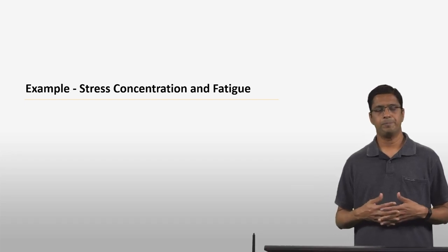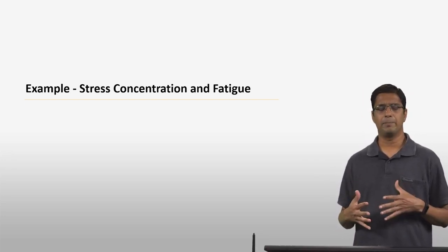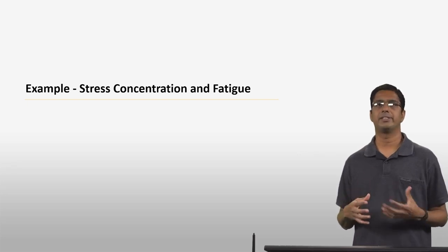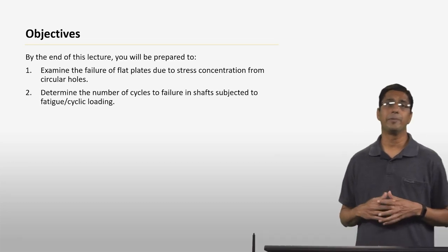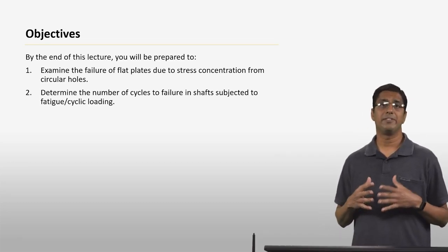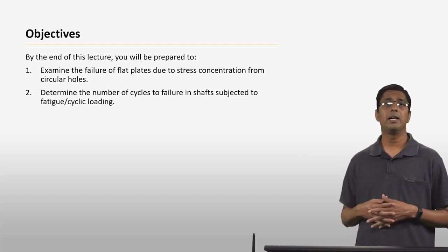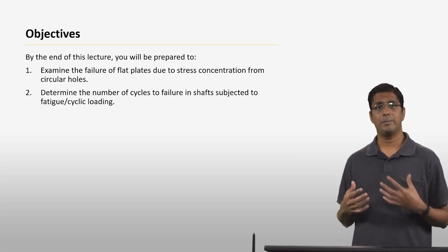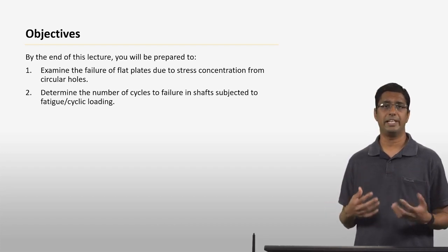Hello, welcome everyone. In today's lecture, we are essentially going to look at two fairly simple examples that involve stress concentrations and fatigue. Okay? So effectively, by the end of this lecture, you will be able to examine the failure of flat plates due to stress concentrations that arise from circular holes, and then you will be able to determine the number of cycles to failure in shafts that are subjected to fatigue and cyclic loading.